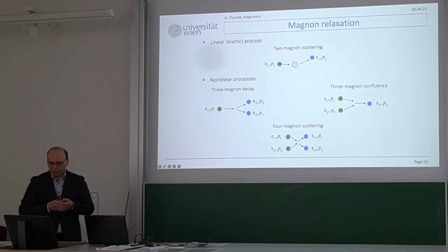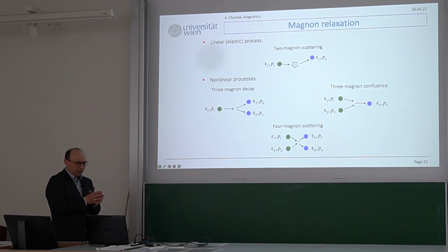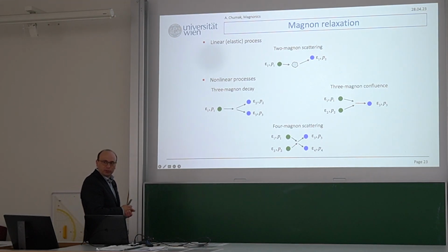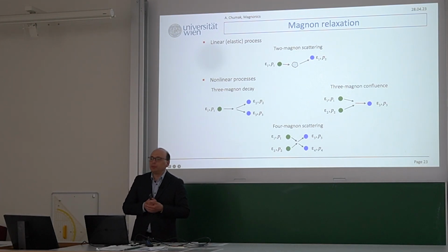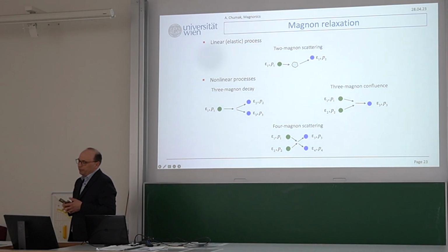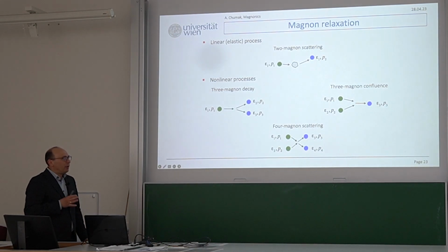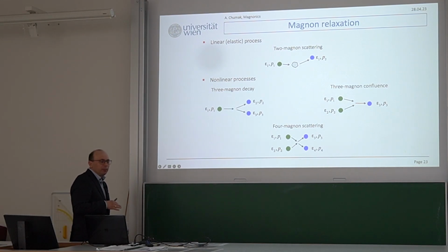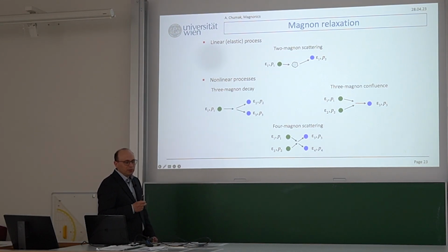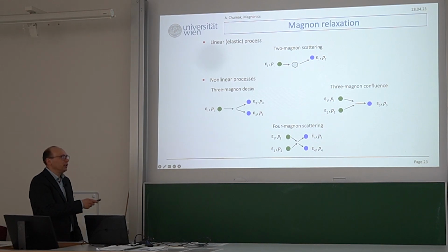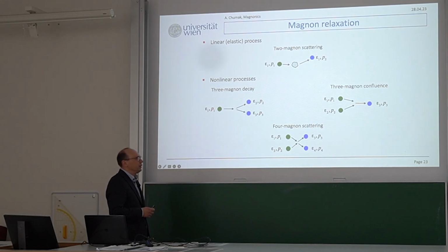The good point is that the threshold, or let's say this mechanism, gets more pronounced for higher applied microwave powers. So if you work in our simplest experiment, just to give you some rough estimation, at 0 dBm most likely there will be no four-magnon scattering, you don't see it. But if you go to 10 dBm, so 10 milliwatts, you already will get scattering. And then it gets stronger. Therefore, that is at macro scale. At nano scale, it all depends on how large your antenna is and how well the characteristic impedance is matched, and so on. So it's all a bit more tricky business. But for us, it's just important to learn that there is this four-magnon scattering mechanism.